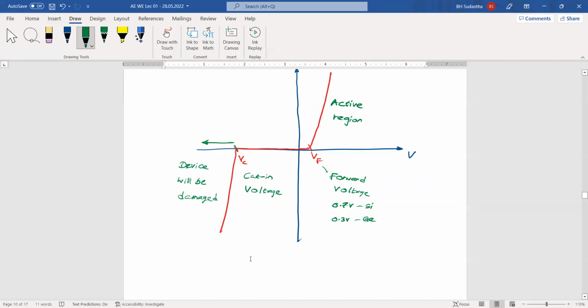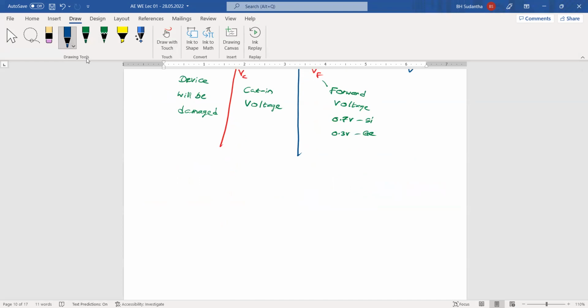And here when we have a diode data sheet, normally in general they give two values. For this 1N4001 diode, the general data sheet provides 1 ampere, 50 volts. This is the device number; all over the world, this is a standard, 1N4001. With this diode, they provide two values for quick reference. What does it mean?